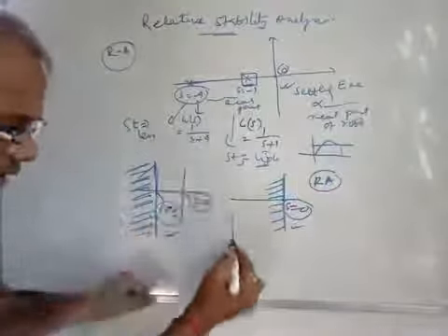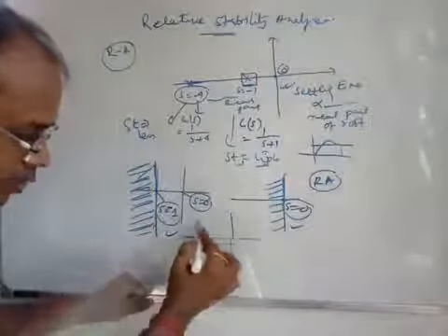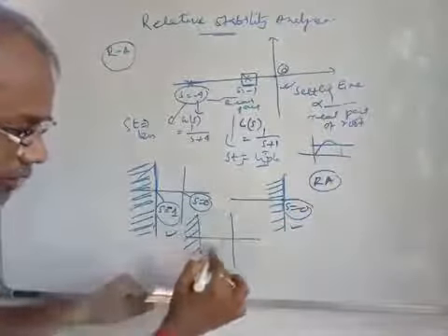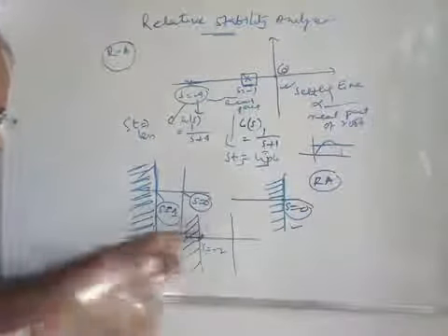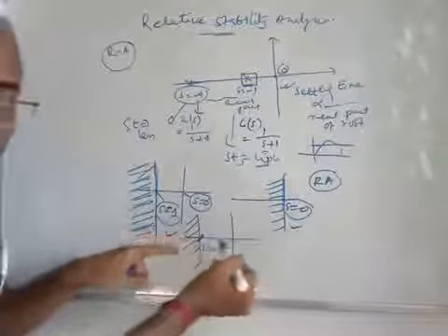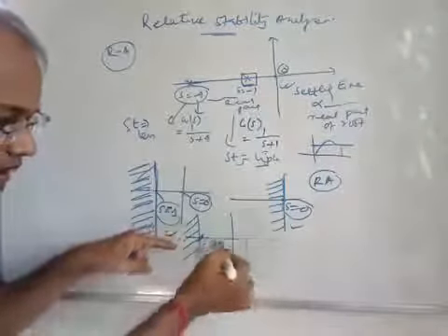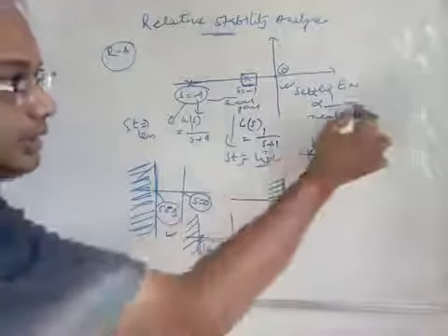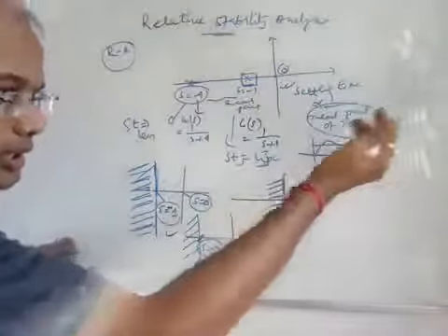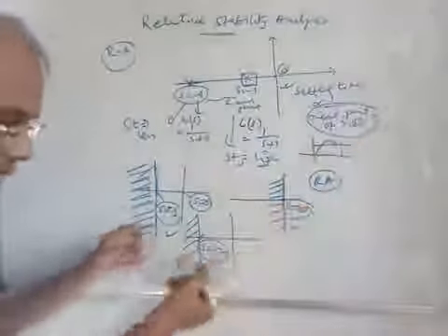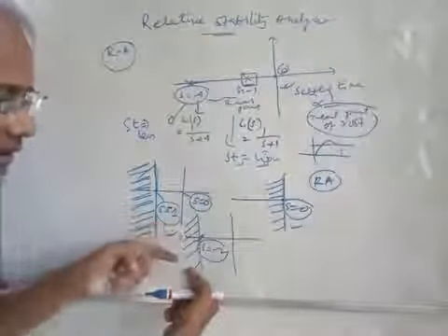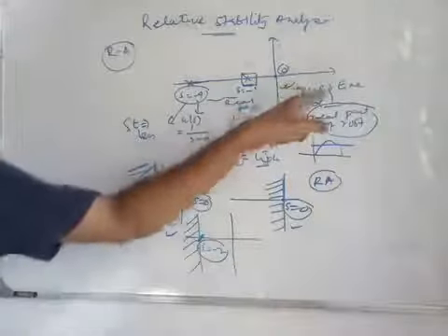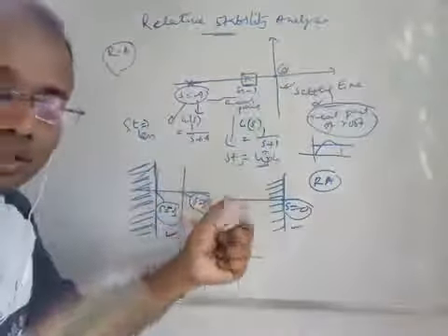Or in certain cases, if it is possible to get all the poles to the left hand side of s equal to -2, you are shifting the real part of the pole. Once the real part of the pole shifts towards the left hand side, the magnitude of the real part of the root increases and the stability is achieved. Till that time the system is relatively more stable and the settling time will be much less.